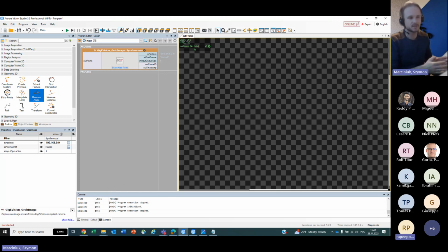You can calibrate this first part even on your desktop. The most important for the whole operation is calibrating perspective and real world units on the station later on. But these two steps are independent. So you can calibrate camera parameters first, later mount your camera on the actual station and continue the process, calibrate perspective and real world units.